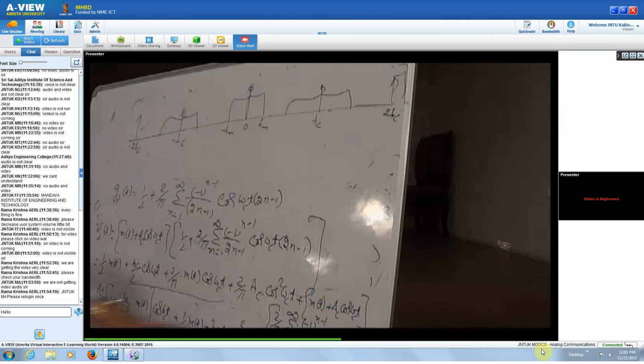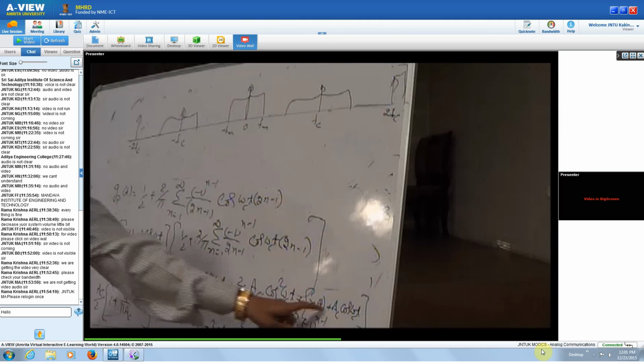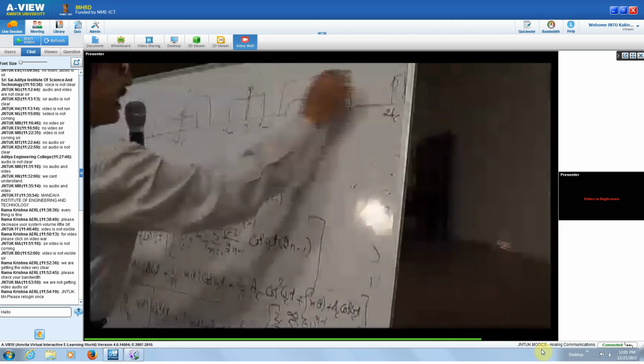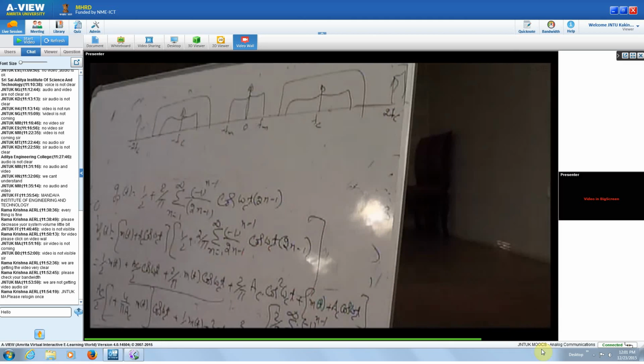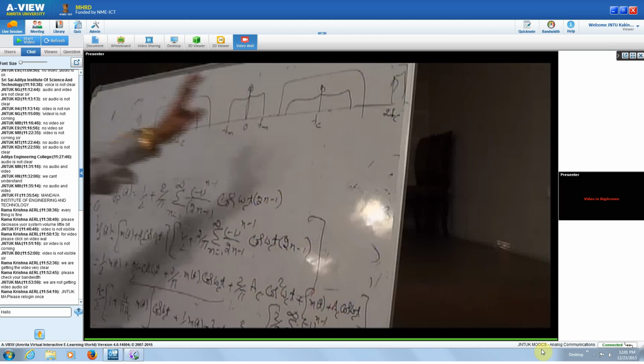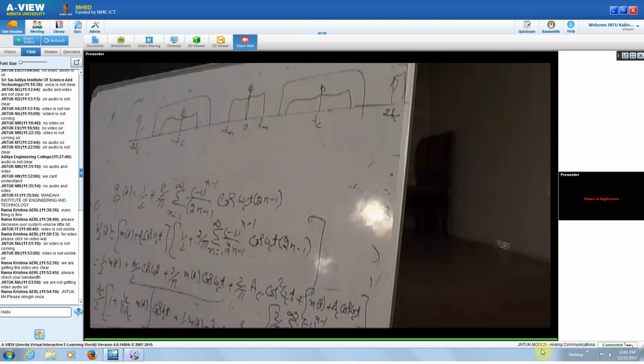With the required modulation also, when you have cos 3 omega ct into m of t, you are having a frequency translated signal at 3 omega c or 3 fc. So all those things will be eliminated by passing this through a band pass filter. This baseband signal has been eliminated, and all high frequency components are also eliminated in this band pass filter. So what is the output?